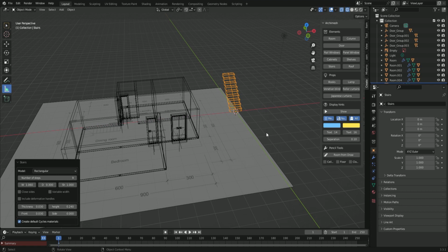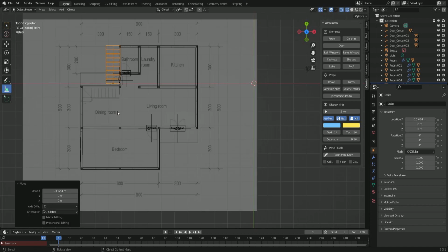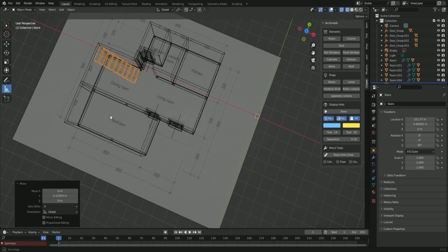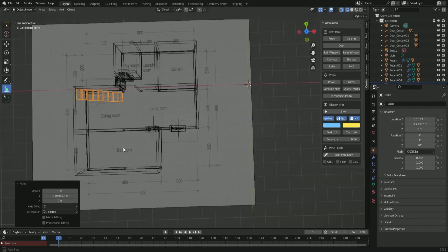So even if you do it once and you see, oh, I need an extra couple of stairs, then just generate a new set, delete that one, generate a new set of stairs, and then obviously try again. That's the only problem. As soon as you move the model, the bottom left options for you to alter the stairs disappear, unfortunately.